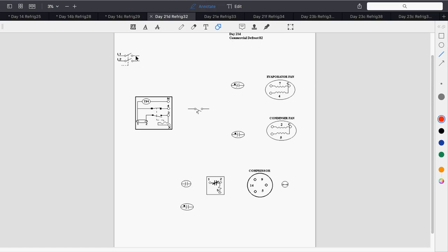Enough power will take the tip of a screwdriver off. Don't ask me how I know. Just remember, when you're in the field working on this stuff, as soon as you have a double pole breaker, you have to shut the breaker off when you reach in here to do something, because both of these are live. It's not like a neutral that's tied into the ground.